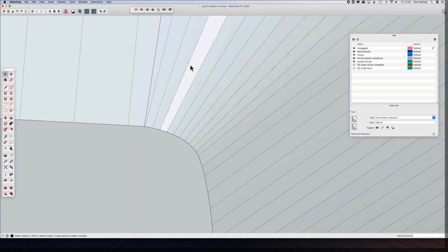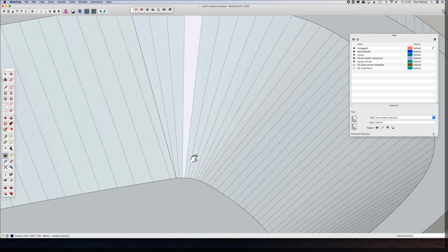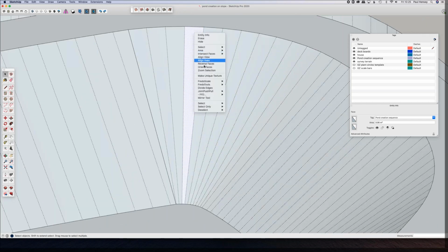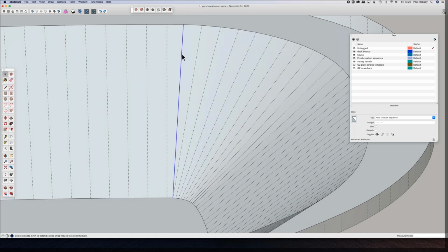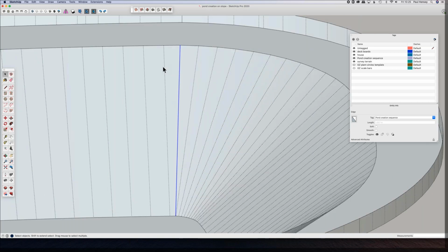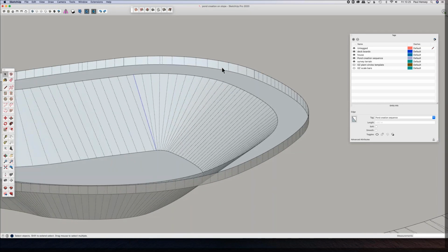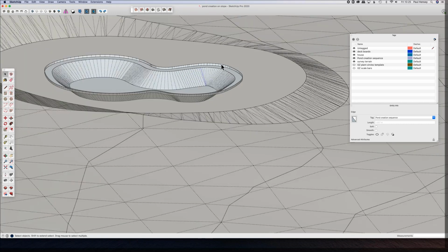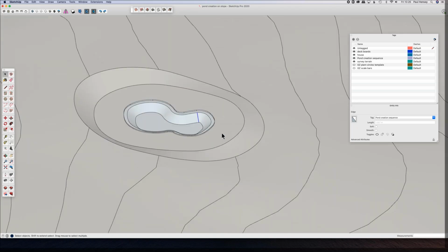Also, I've noticed that when I select this geometry, it has created it, it just caused this one to reverse. So if I reverse that face back, I probably have a clean piece of geometry. This one has just given me a solid line, not a dotted line. If I use the Erase tool and hold down the Shift key and drag across, that's the same as using the hide command. Now, I'm just going to go to View, Show Hidden Geometry and switch it off.